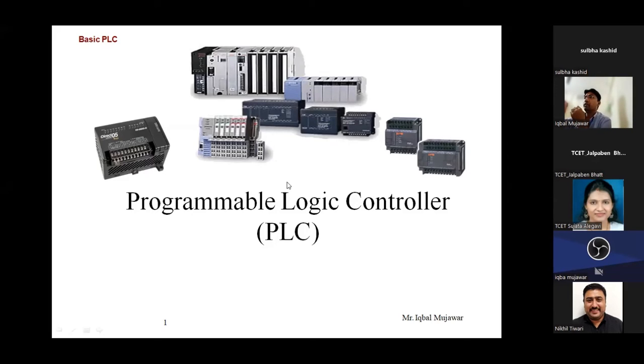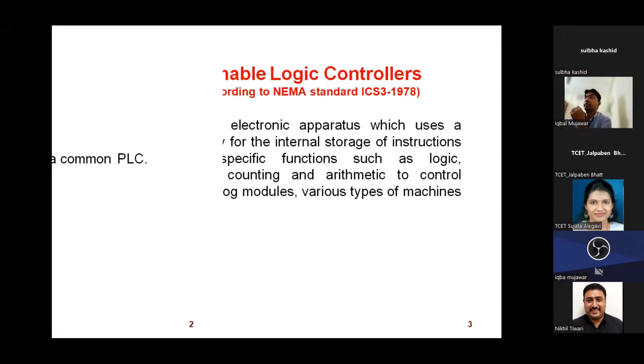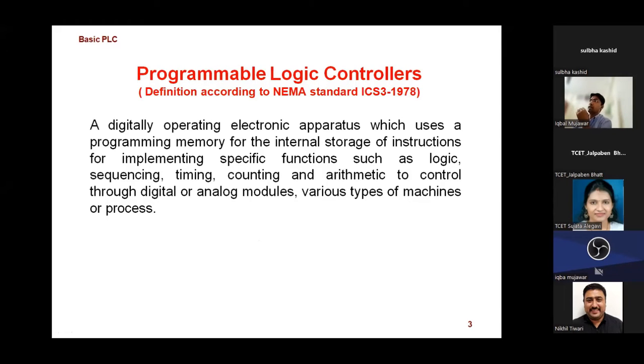Then regarding the PLC, as we can see here, based on the NEMA standard, that is the National Electrical Manufacturers Association, based in North America, we mention what a PLC is. A PLC is nothing but a digital operating electronic apparatus. It is an apparatus like a controller, available in the market, which uses programmable memory for internal storage of instructions, to implement specific functions such as logic, sequencing, timing, counting, and arithmetic, which are required to control processes, digital or analog, in various types of machines and processes.